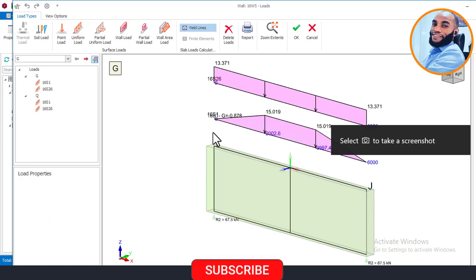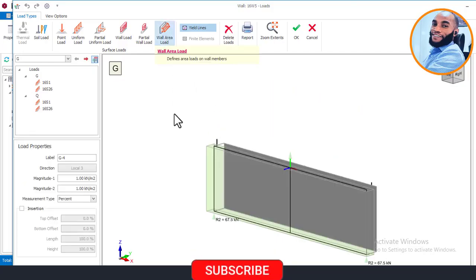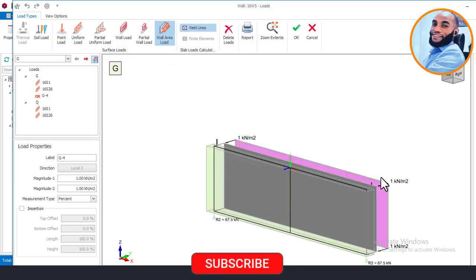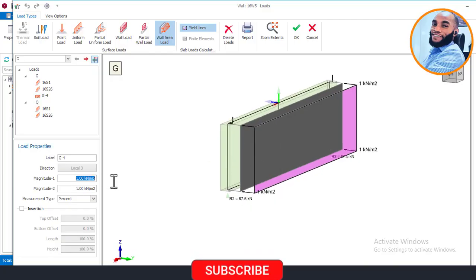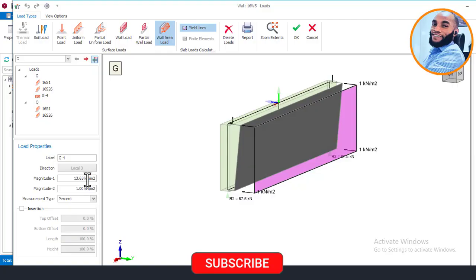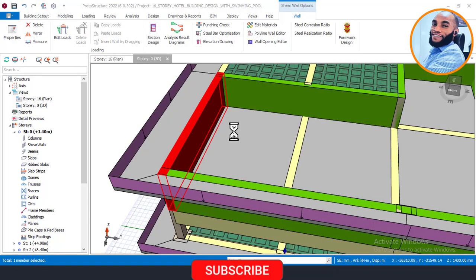Now if maybe you missed the other parts, or you didn't capture what we did before, since I'm going to repeat the same thing I did before, you just have to catch it up here. So I'll come again, click on the area load here, and then click on the wall icon here, and you will see your surface area load display here. Now on this area load, I will specify my load, which is what? 13.63 as calculated. This is not a default value for design, but for this particular building and for this pool, this is the load of water that we have. Okay, I'll come here and click on update here, and it will change. I'll come here and click on what? Okay.